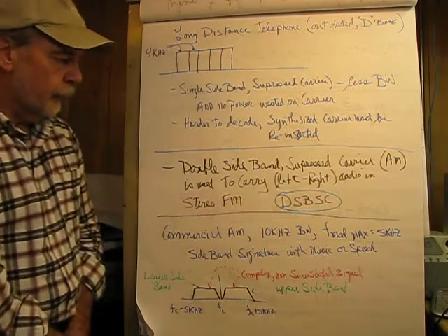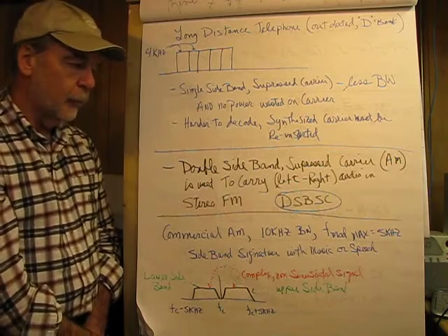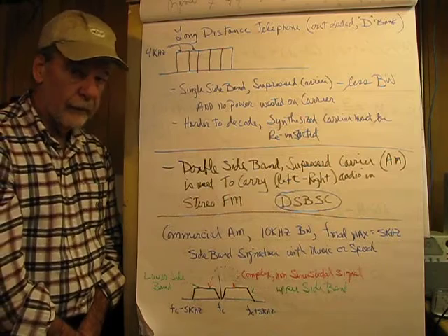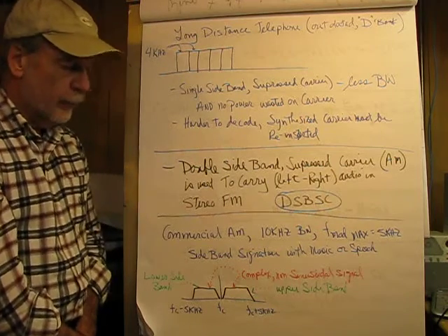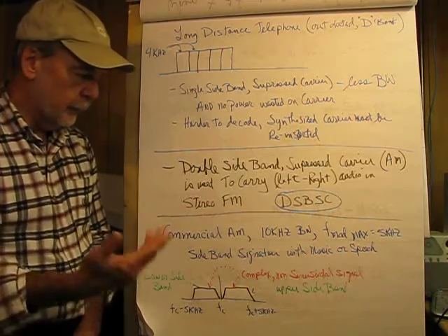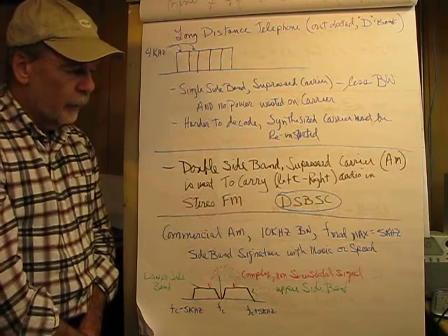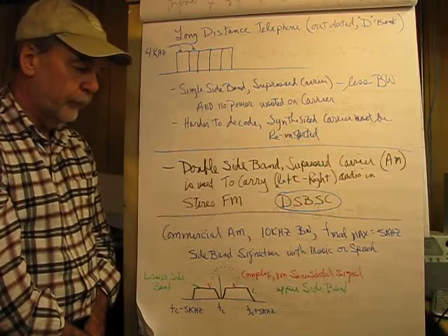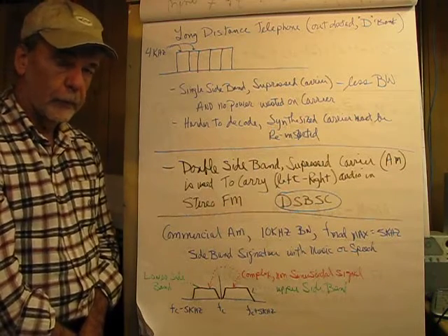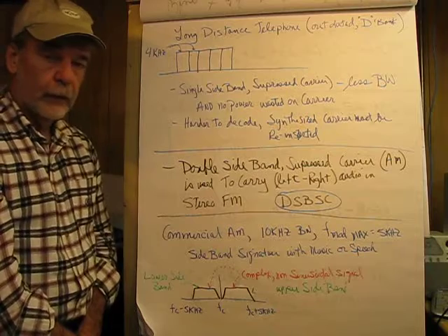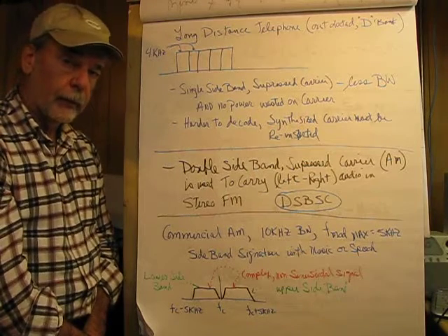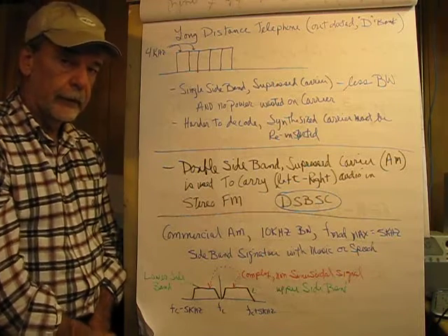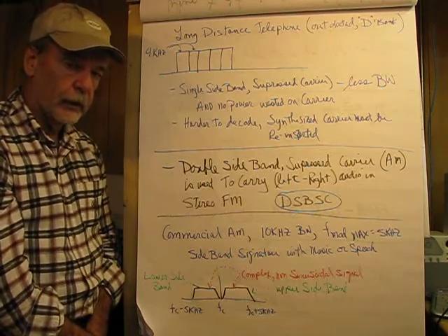Now we have another type of AM which most people don't realize exists, and that associates with FM, frequency modulation, and that'll be coming up as a topic soon. But there's a left plus right component, which is the monophonic component, and a left minus right component, and if you add those two together you get 2L, so that would be the left channel. And if you invert one and add them together, you'll get 2R, which is the right channel.